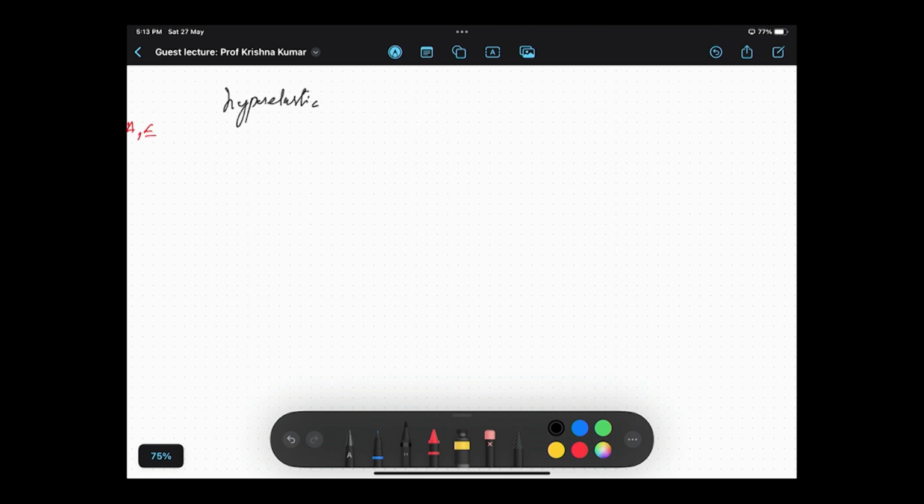As I told you, there are two ways in which a material can broadly behave. One is, if this is stress and this is strain, linear. Many bones you can model like this. On the other hand, the material may not behave like this, but like that. It can harden later, or it can soften later, and so on. So this is non-linear. When I want to characterize it, I can say stress is proportional to strain, and so E. I can just fit one curve for this. It can be, say, cubic or a combination of them.